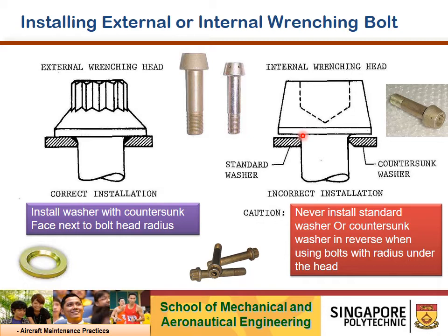So follow the illustrated parts catalog or aircraft maintenance manual properly. If you are installing an external wrenching bolt, definitely they will mention what type of washer to use, and based on the part number, order that part number. Alright, that's referring to the illustrated parts catalog, IPC.